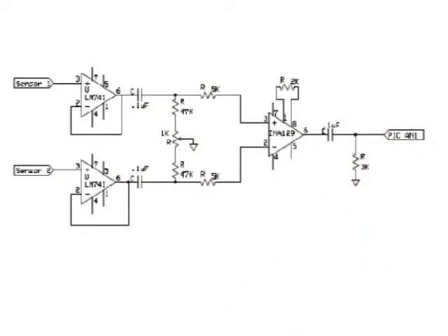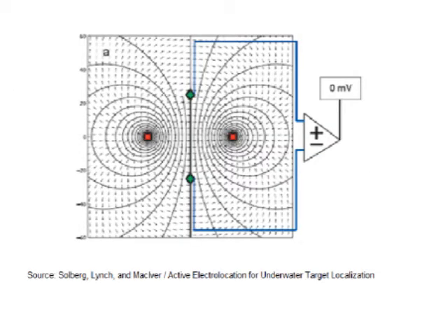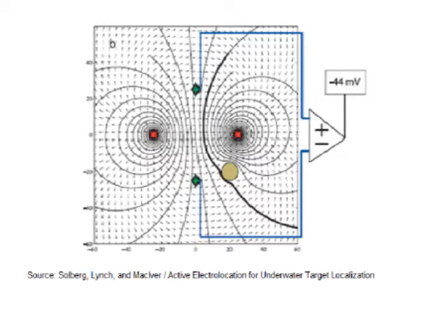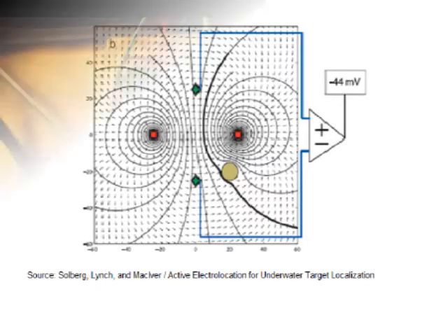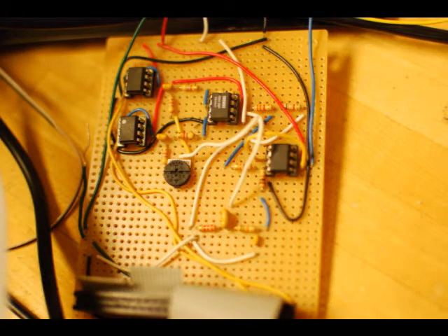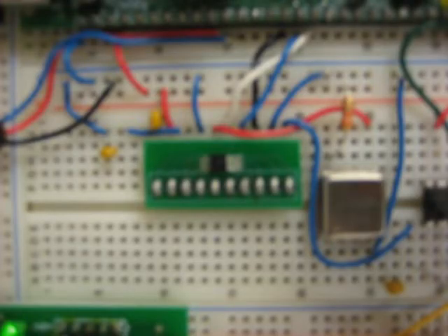The sensed wave is generated by reading in the two waves at the sensor electrodes and comparing their signals. This is done using an instrumentation amplifier, which multiplies the difference between the two signals by a fixed gain. If the waves are identical, then the output is nearly zero, with greater differences between the waves corresponding to larger amplitude changes. To read in the signal to the PIC, we must level shift the voltage so that it ranges from 0 to 3.3 volts, the acceptable range of the ADC.